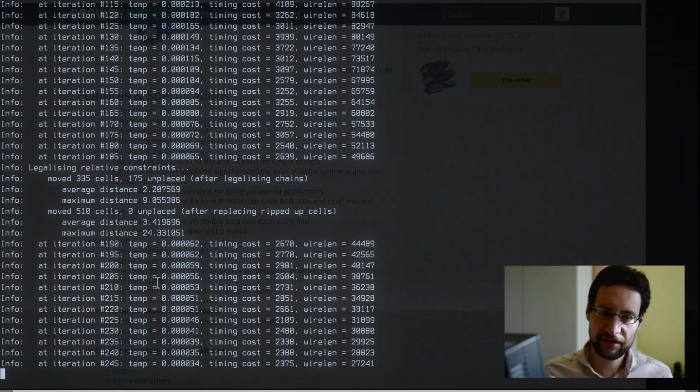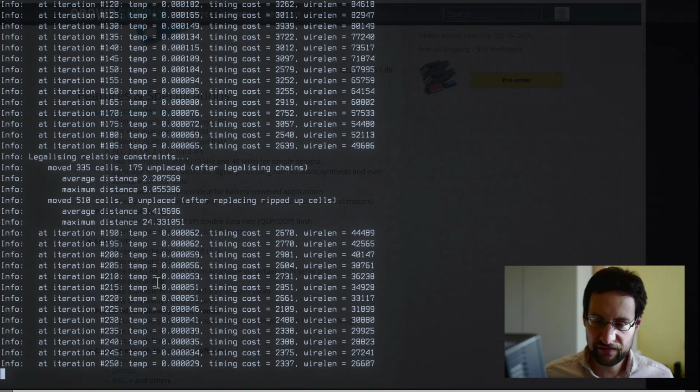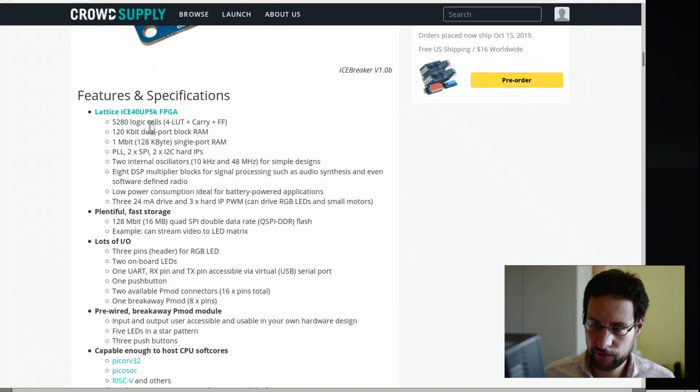And if you have ideas and wishes what to do, you see we are a little bit constrained here. Even text mode will be a little bit challenging. What is needed for this is to create a character generator, meaning we have some byte in memory like A, and then we need a character generator. Even this is challenging because we are running a little bit out of memory and logic elements.